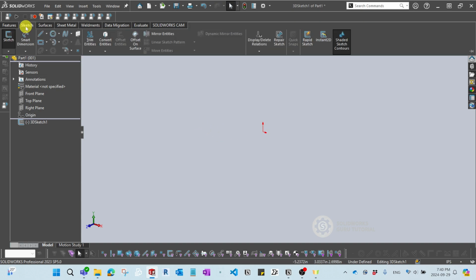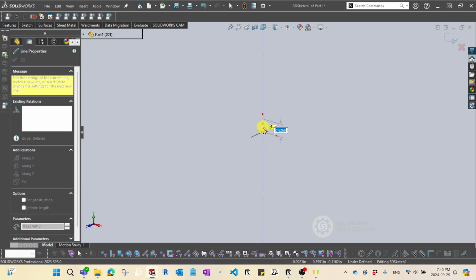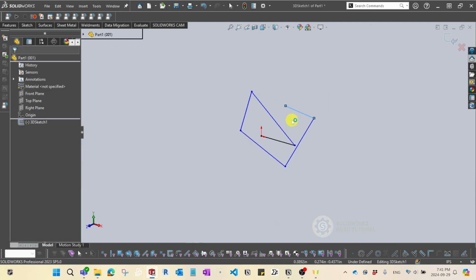So then if you go to a sketch and just try to draw a line, I'm just gonna start from the origin, and as you can see, two additional arrows have been created. What that means is you can only draw the lines in the X and Y direction. If you look at this origin point, these two arrows are directing to the X and Y direction. So no matter what you do from here, you can only draw the lines on the X-Y plane, okay?